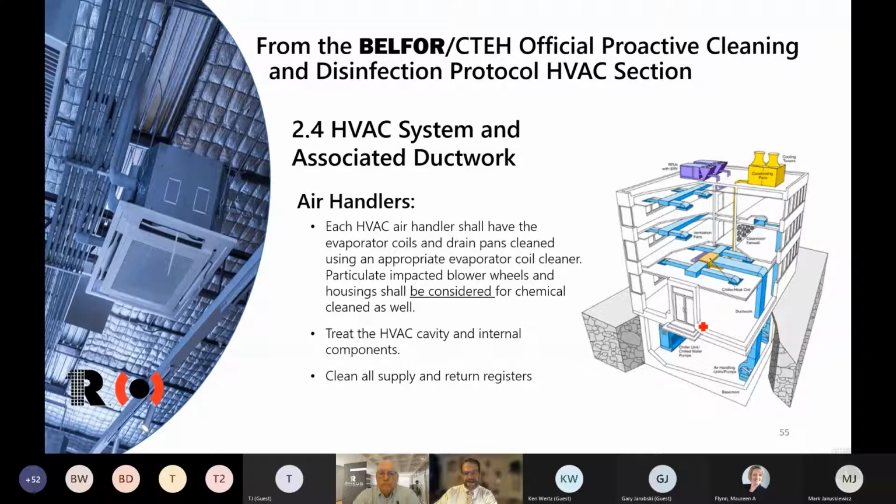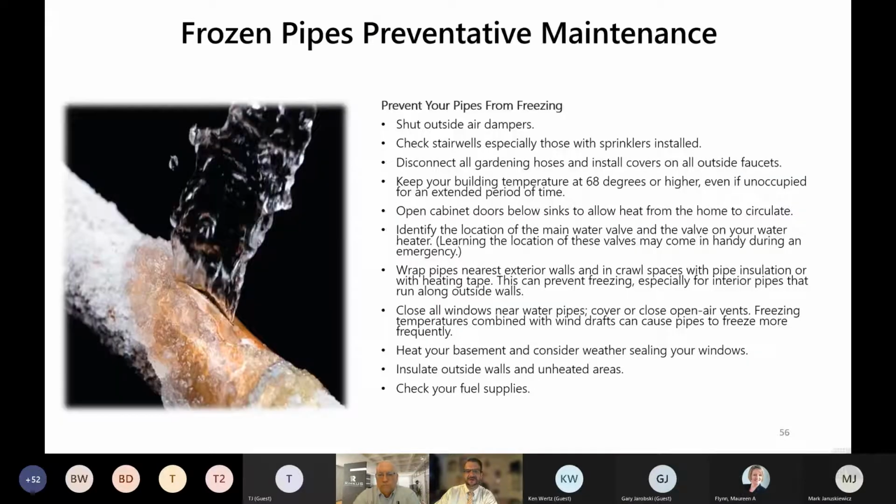And look, I'm not going to get into whether the systems are already dirty. They're not dirty. Many systems over a period of time become dirty. That's just the nature of the beast. What I would encourage everyone to do is absolutely check to make sure that the filter banks are intact, that the high level of filtration is in place, and check the outside air dampers to see what position they're in. That's going to require work, to make sure, and just have a real understanding of where these air conditioning or heating systems are at.